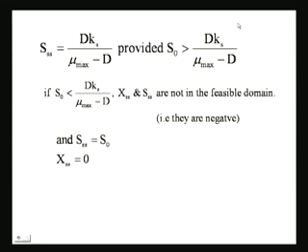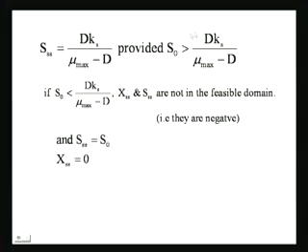So, the second criterion that we get, so there are two criteria that we have to satisfy. One is that the dilution rate of the system has to be less than mu max, that is, the residence time, which is 1 over the dilution rate, has to be greater than 1 over mu max. And the second criterion we get is given here: S naught, which is the initial concentration of substrate in the feed, has to be greater than this quantity, dKs over mu max minus D. Okay. So, both of these criteria have to be satisfied in order to be able to produce cells, so that your XSS is greater than 0. Okay. Both of these criteria have to be satisfied. Fine.